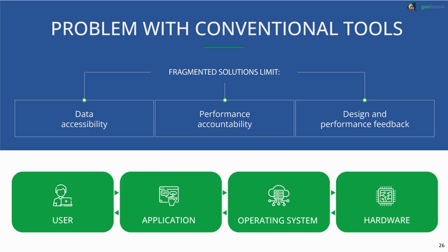Because oftentimes what we've seen is these building operators, they're doing their job, but they're somewhat misaligned with the person paying the energy bill, right? Because their job is to keep the lights on and make sure that building's comfortable. But maybe they're running the backup equipment more than they need to, and maybe that system COP isn't as strong as what was originally intended.